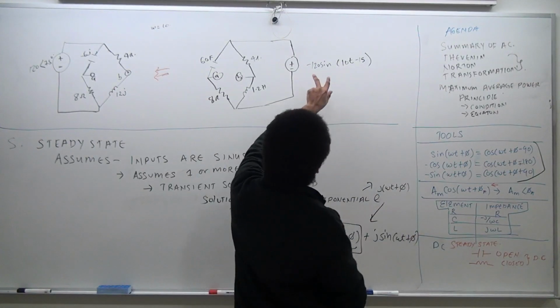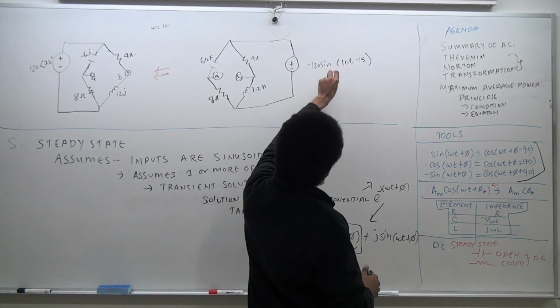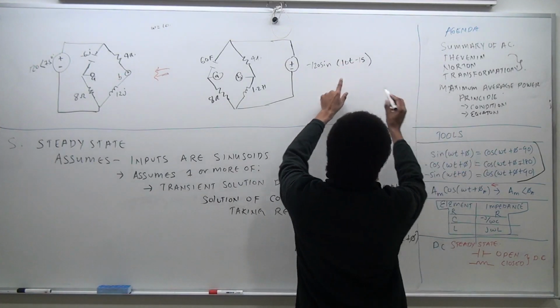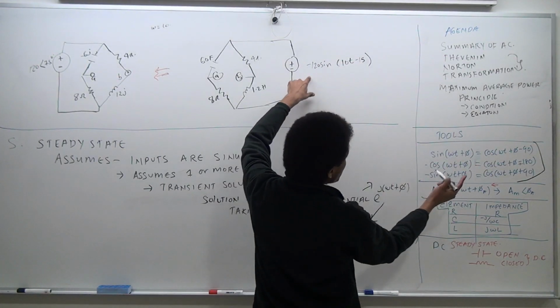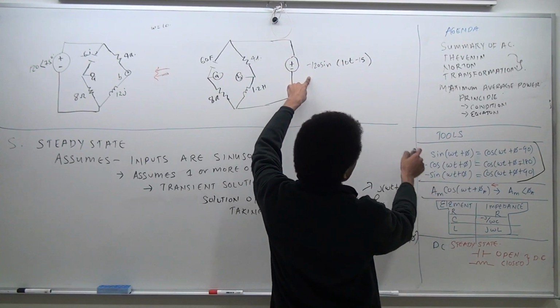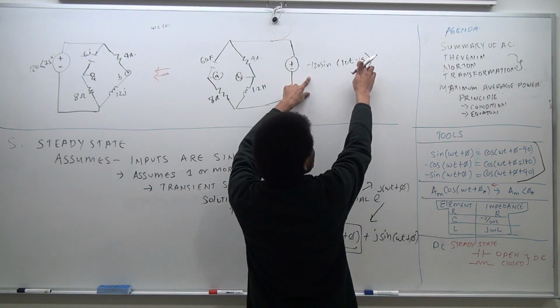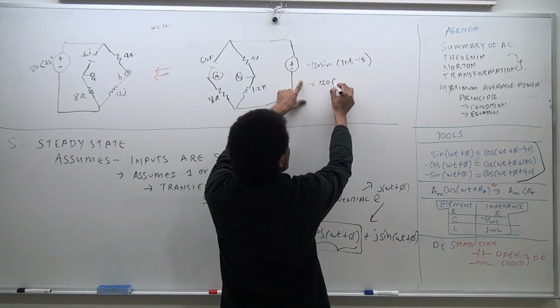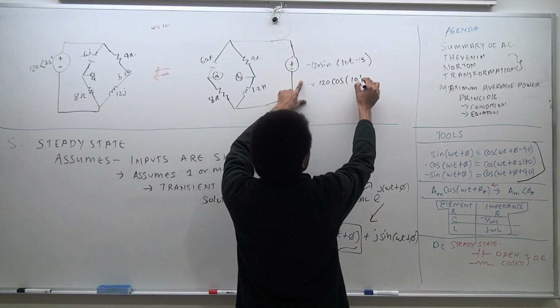So these are the three formulas that need to be memorized, or at least you should be very, very familiar with. So in this case, we are given 120 sine(10t minus 15). So the first step would be to convert this, using number 3, we just add 90 to the argument of the sinusoidal function. So you're going to get, this guy is equivalent to 120 cos 10t.